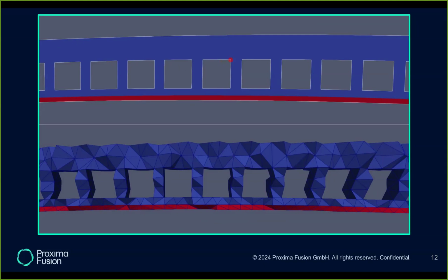The blue is Eurofer, which is a futuristic metal alloy developed by ITER, I believe. No, developed by the fusion community, and it is very suitable for this kind of application. And the small red layer is 2 millimeters in this picture. It's tungsten, which has other interesting properties that make it suitable for being the first layer, called the armor. So it's the first layer between the plasma and the rest of the machine.